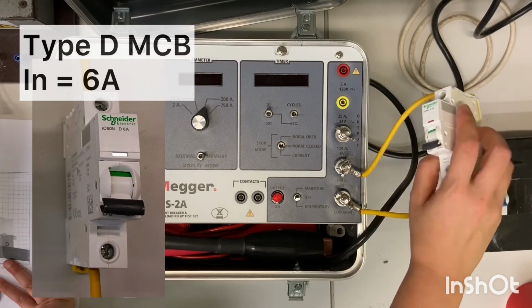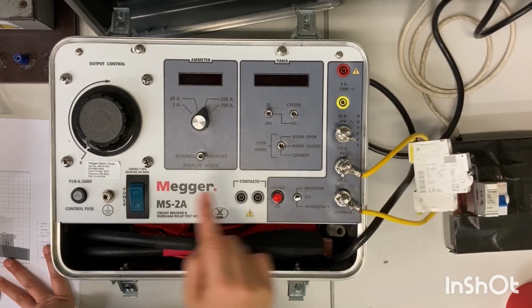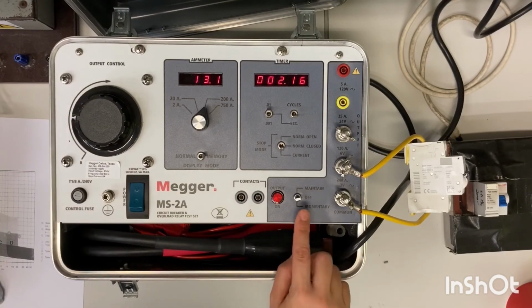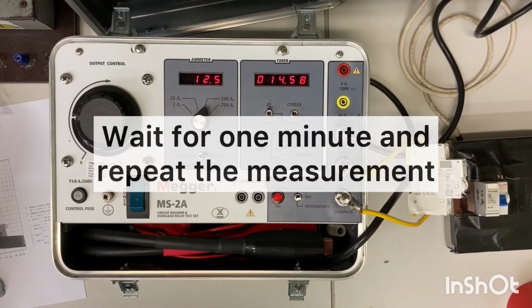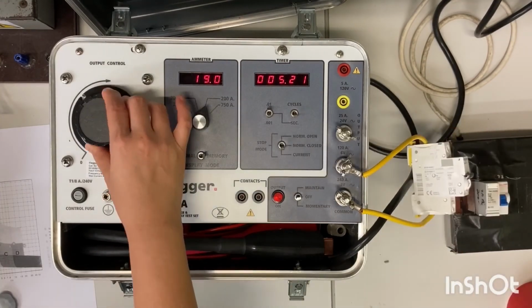Now we can do the same testing for the type D MCB. We follow the same procedures, turn on the mega test set, and we press momentary and adjust the required current value. Then press maintain and inject the current to the MCB, and wait for the MCB to trip. We heard the click sound, and the MCB has just tripped. So once again, record down the data and wait for 1 minute for another measurement.